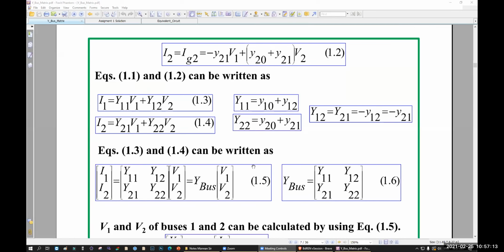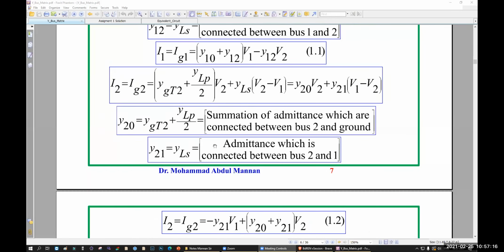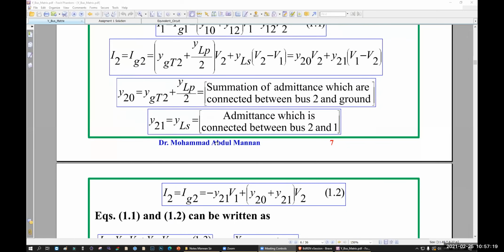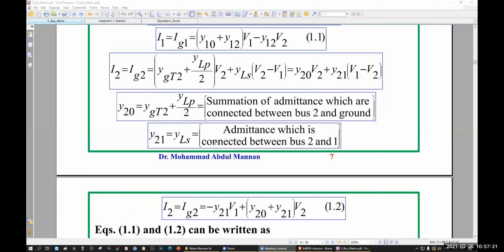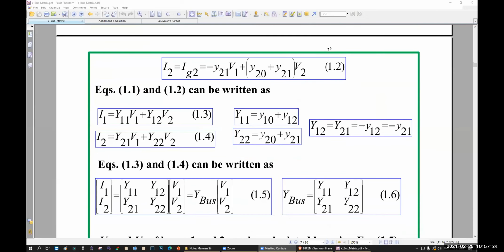Let's do one math. Oh, before that, why is the Y bus matrix necessary? You can ask. The Y bus matrix is necessary because of the nodal equation that I was talking about here. This is the nodal equation. Nodal equation means if you have multiple currents, multiple voltages, multiple admittances, you can write like this. I1, I2 in matrix form. See, I1, I2 is equal to Y11, Y21, Y12, Y22 times V1, V2.